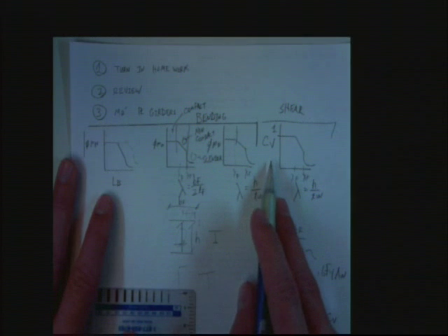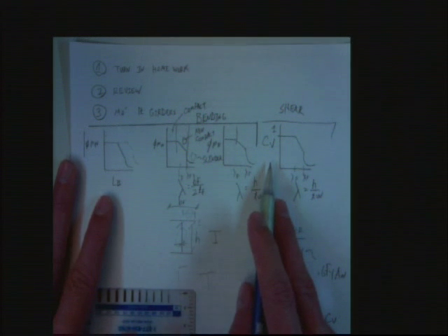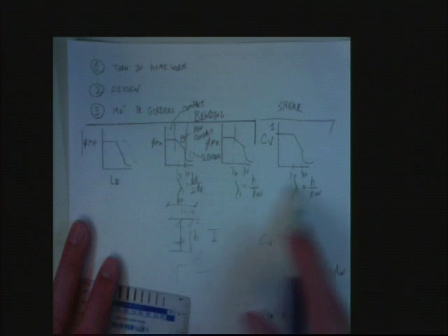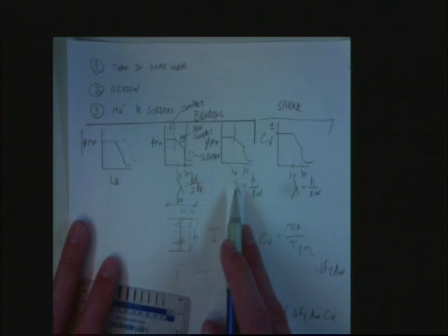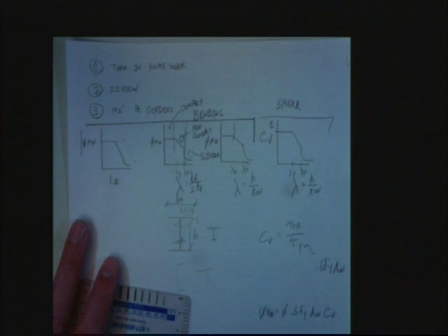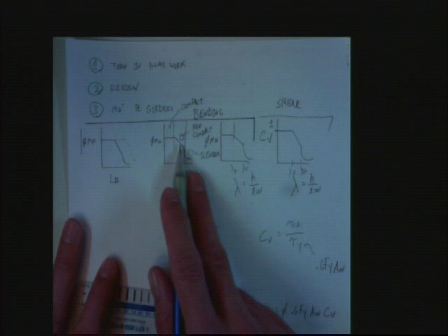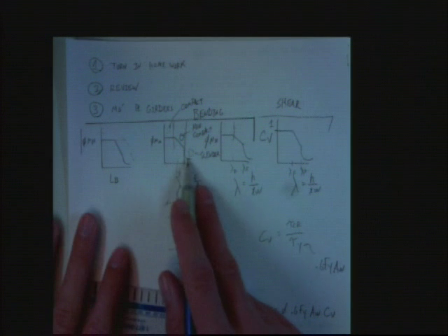Now, let me give you a piece of advice. Whenever you're doing a plate girder, a design, an analysis, whatever, figure out which zone you're in. That should be your first step. Because then if you start to make decisions, like, let's say I'm here, and I'm going to change the size of my flange, that's going to have a somewhat linear impact on my moment. But if I'm down here, I am off the edge of the cliff, ladies and gentlemen. And small changes in my flange can make huge impacts on my moment capacity. Does that make sense?